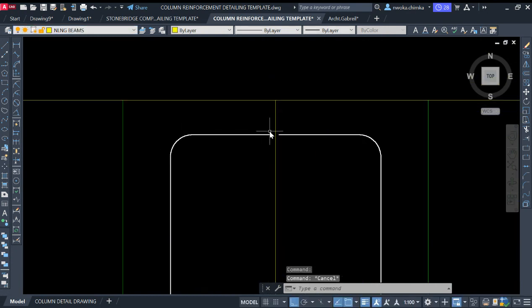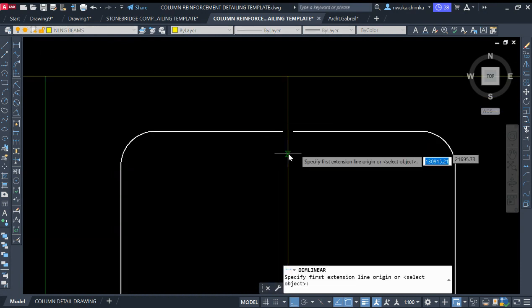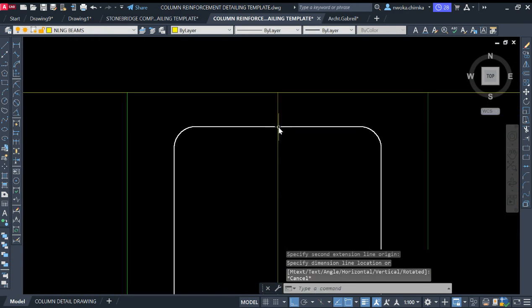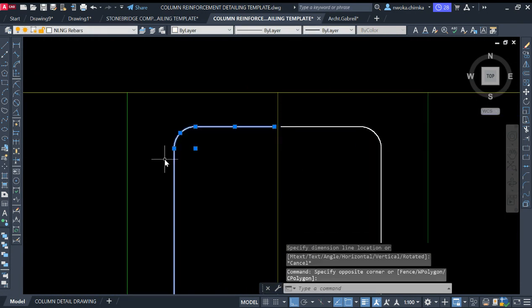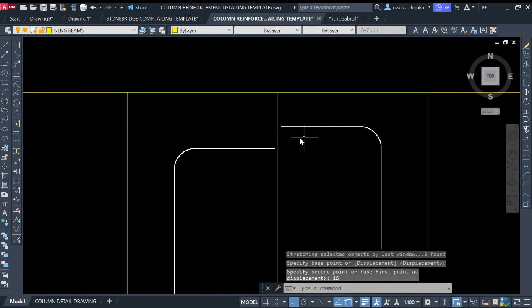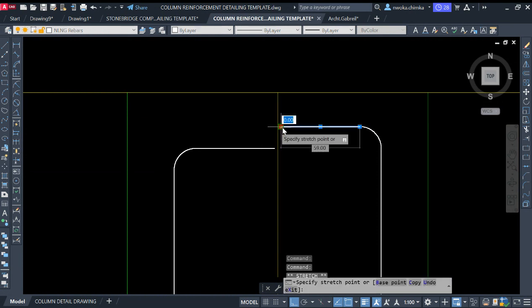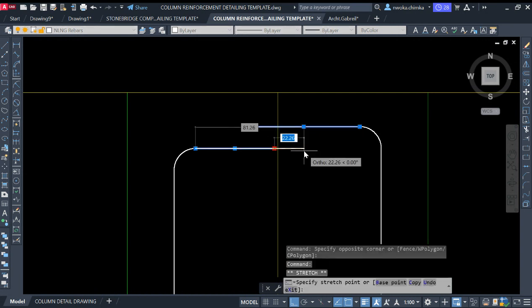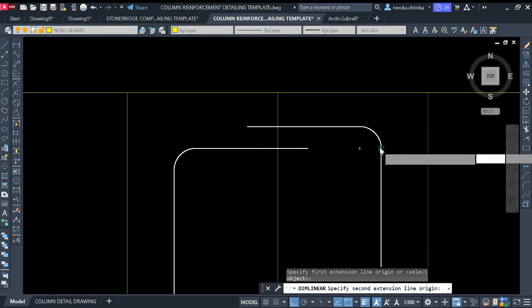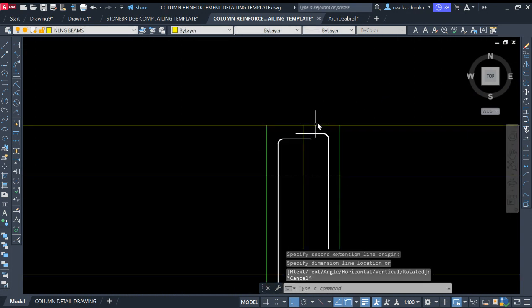Okay. Now this place tends to be too close, because the spacing here is too small. You can see that it's just 5 millimeter. So it's too small. Because of that, we'll bring this downward by the size of the reinforcement, which is 16. Since we have gotten these changes in height, we'll now extend this from 75 to make it 100. So add 25 to it. Also the same thing here, add 25 to it. So check this. If you check this, this is now giving us 100, as you can see here. This is 100 bending. So this is okay.